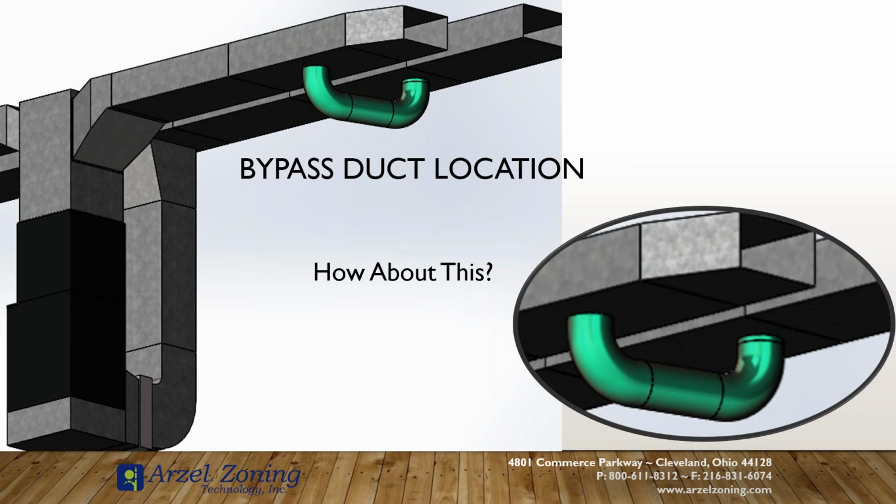That way you're coming off of the majority of the airflow, but at the same time, you've given it the opportunity to go to the home before it bypasses, if those runs between there and the furnace are calling. So you shed some BTUs through those other runs, and instead of dumping the full BTU load back into the return for that pipe.